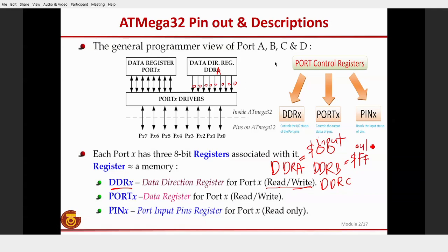It is assigned as an output, meaning that whatever value from our microprocessor, we output it, we give it to port B. But for DDR-A, we use it as input, meaning that we read from the external, for example, we read from a switch, or from a sensor over here in port A. So if it is used as port B, DDR-B needs to be assigned as FF first, meaning that we tell port B, you work as an output.